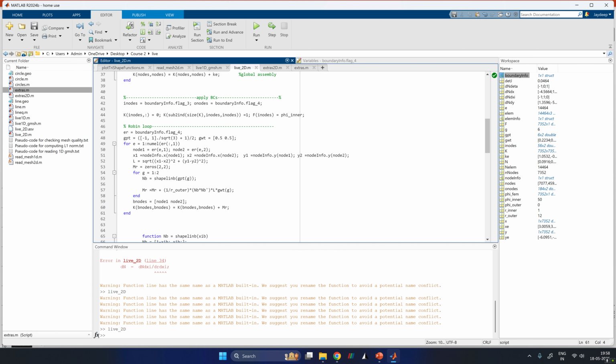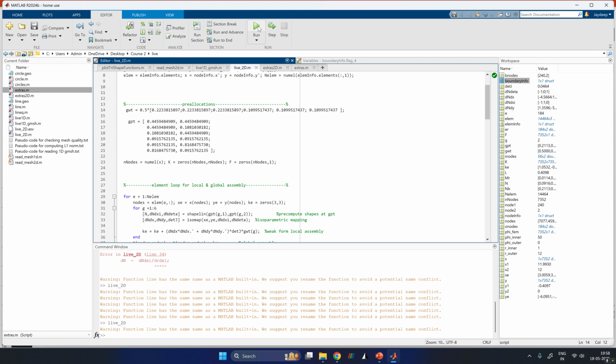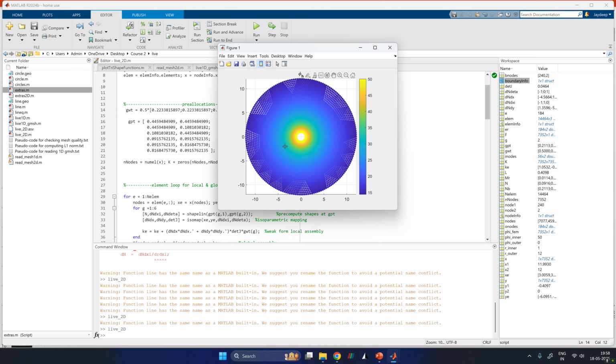There's probably some issue here. Yes, there's some issue. I think I did not multiply the Gauss weights by 0.5. Yes, that's right. So this is the solution where you get almost 14.3 at the outlet. So you can just derive this analytically, and we will also look at the flux at the boundary. So this is our solution, and you can just compute analytically the flux at the boundary. And so this flux has to be around 90.